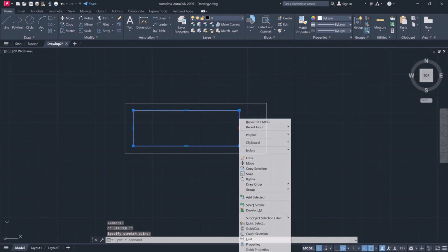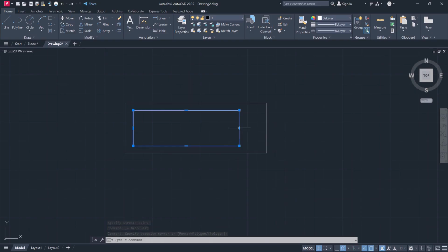I'll place this here and right-click. I'll position it on this point. I'll select Convert to Arc. Then I'll choose the Circle tool. And I'll draw a circle here as well. As you can see, the parts of this bathtub are separate from each other. This rectangle around it is separate. This is a separate polyline, and this is a separate circle.